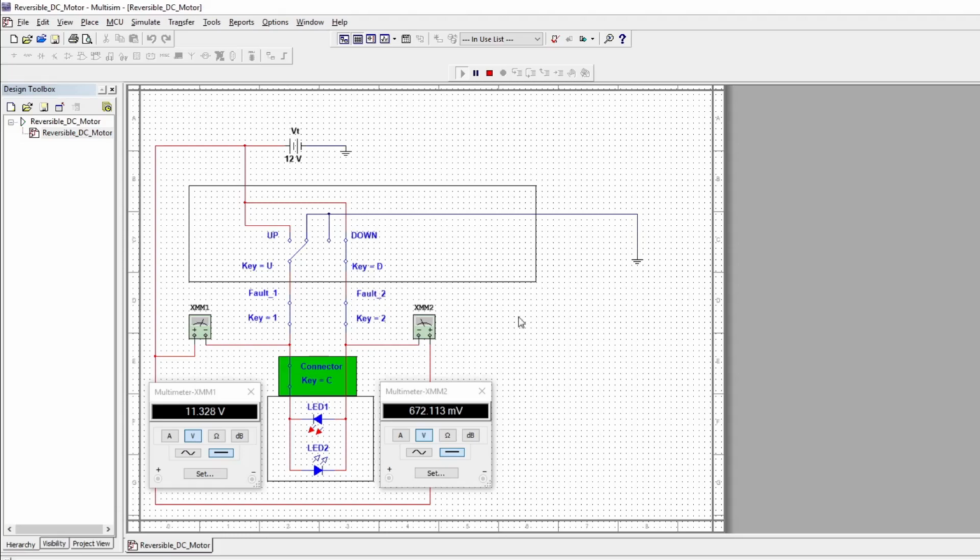You're doing a lot of voltmeter lead moving around, positive to negative, switching around pins. So it's a lot more difficult if you have to do it that way. But you can still get a lot done by simply connecting the voltmeters this way and then just probing those two lines, whether you're all the way down at the motor, ideal because you can just check more on the same test, or up here at the switch. Just understand, that's an initial test.